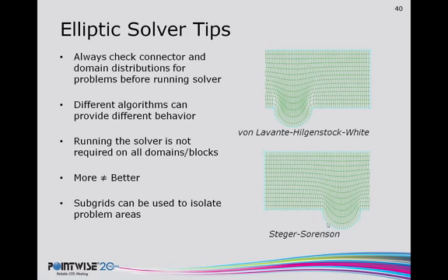And along those lines, running the solver for more iterations is not going to give you a higher quality grid. In fact, in some cases, that can wreck a grid that's perfectly good from the onset.